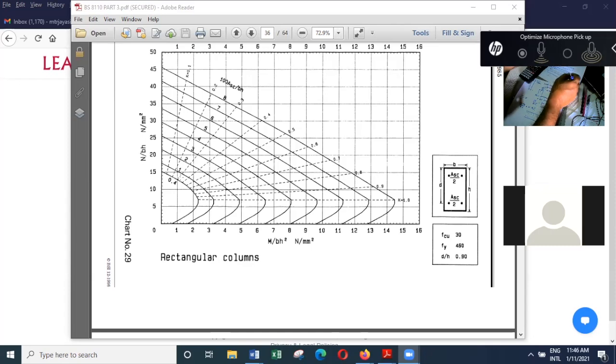If the stresses are significantly low, then you might end up with slightly lower reinforcement for the next 1 meter. But on the other hand, in these walls, the stresses will always reverse. Also, in a shear wall the axial load dominates. So unless the moments are very large, this reinforcement cannot be reduced.